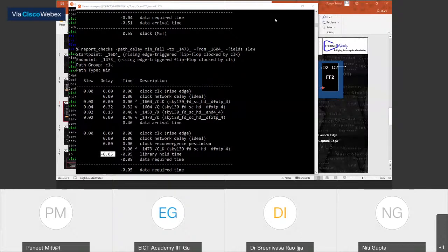So what will be the maximum frequency over which my design can work? Which report suits best to answer this? If you're talking about STA, think in this way: you will not be able to do STA unless you tell the clock frequency.